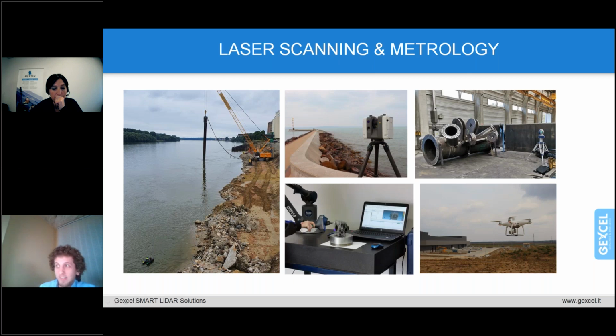And maybe the most interesting and the biggest project of the previous year, on the top right corner, we have our laser tracker, and you can see one of the elements for the new athletic stadium for Budapest, where we provided the quality control for each manufactured piece fitted and constructed on the site. Each of these more than 10-ton steel elements had to be within 2 millimeters absolute tolerance, and the whole athletic stadium fitted within 2 centimeters of the planned state and the as-built, which is something even we did not think was possible to achieve.